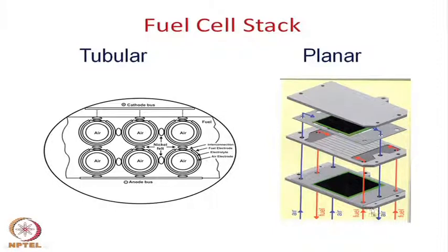Okay. So, through one of those holes the fuel enters and comes on this surface, the top surface, because the bottom here is the anode and the top of the black surface is actually the cathode. So, this top surface on this plate is actually the channels for the fuel, and the bottom surface on this plate is actually for the air. So, that is what is happening here.